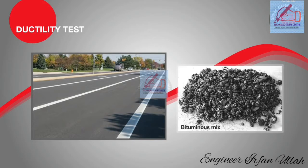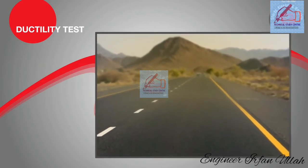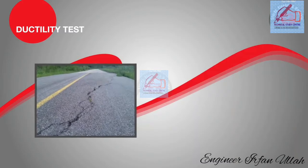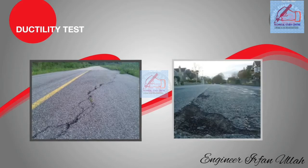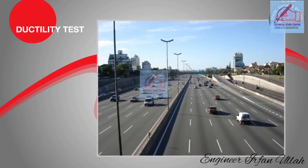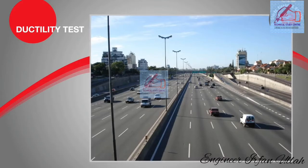a ductile thin film around the aggregates. This serves as better physical locking of the aggregates. The binder material, which does not possess sufficient ductility, would crack and spoil the pavement surface. The right ductility value of bitumen binder is an essential requirement for making good highways.